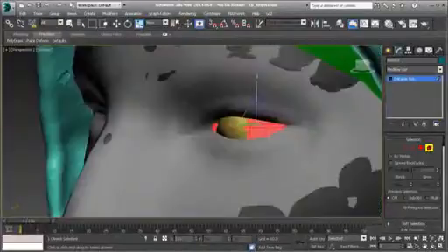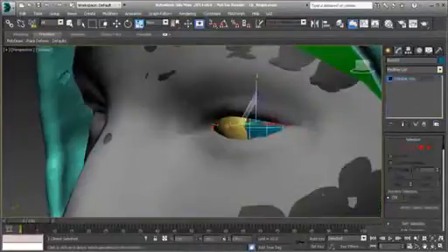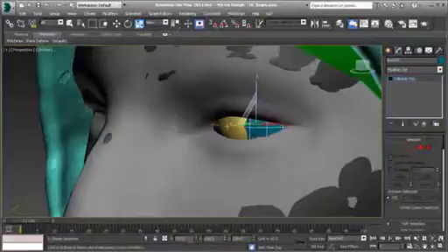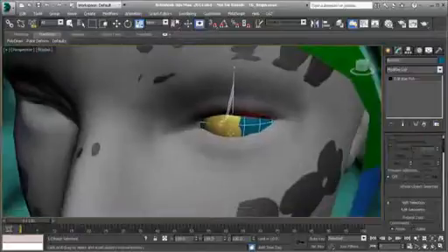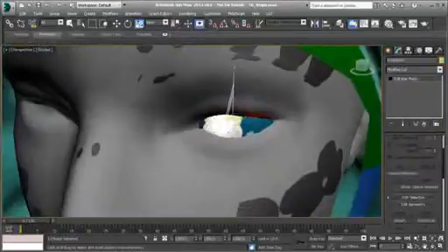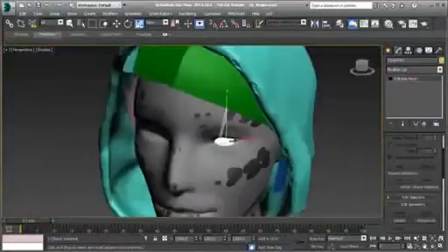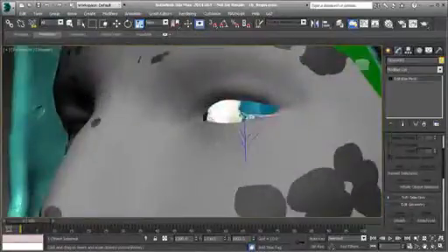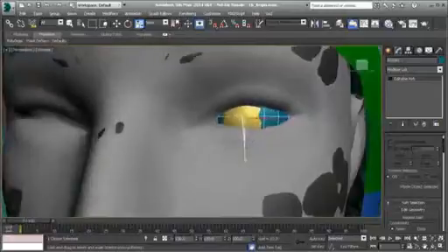And then we'll select both of those, change their color. And I'll just put in a quick gray material. There we go. So we've got the eyes. If you like, you can go ahead and go to element mode. With all the polygons selected, you can change their smoothing group to where everything is on a single smoothing group. So clear all, and then set it to smoothing group 1. Now you'll see that our eyes look nice and smooth here.